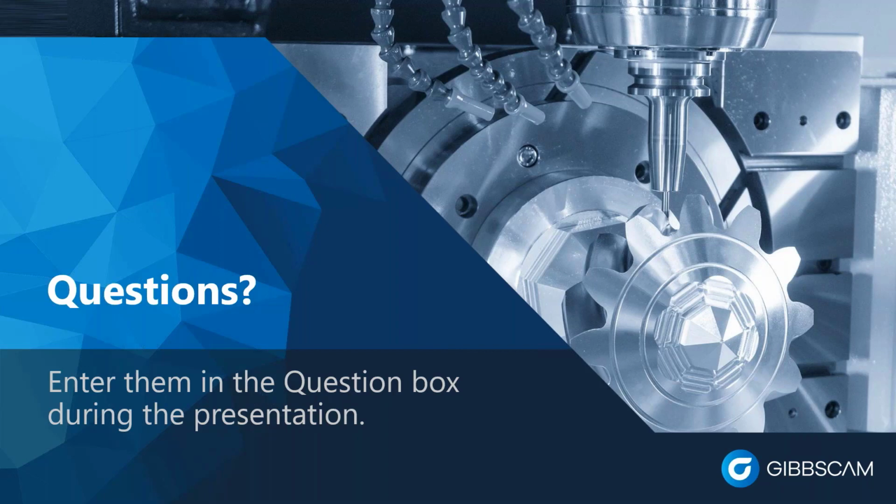Some customers actually have a 5-axis machine but only got a 3-axis post because they didn't have the 5-axis software, but eventually add the 5-axis software, and then in that case, your post does need to be upgraded to add 5-axis capability. And then the more common ones are what you just talked about, the TCP and the DWFOs. In order to support those, your software does it, if your machine can do it, and if your post doesn't already have that support in there, then you'll need to get your post upgraded.